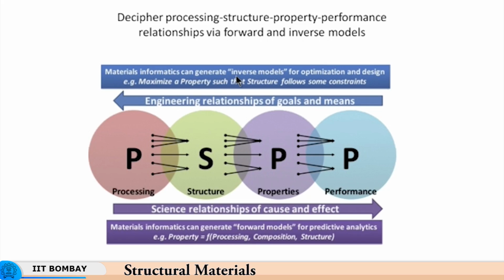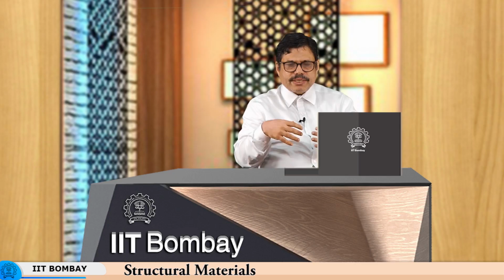If I get a fine grain size, you know that the Hall-Petch relation correlates grain size with the yield strength of the material, and the larger the yield strength, usually the larger the tensile strength as well. So, I will look for a fine grain size. I will also look for phases in the material which are ductile in nature, meaning which do not impede ductility.